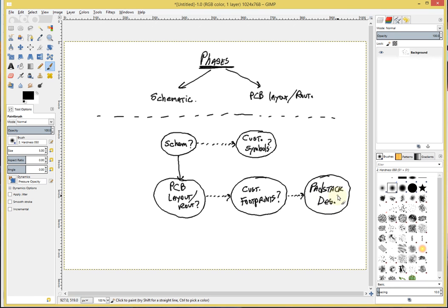Then you use these pad files to create the footprint itself. Once you have created it, you can use that footprint many times on your PCB board, and you attach that footprint to components in your schematic software.